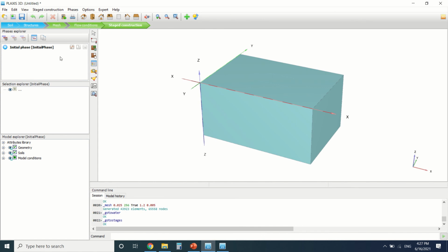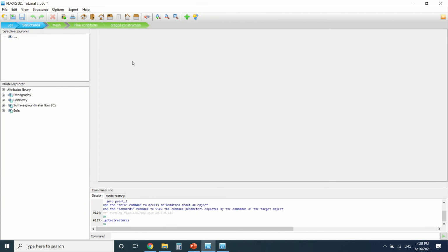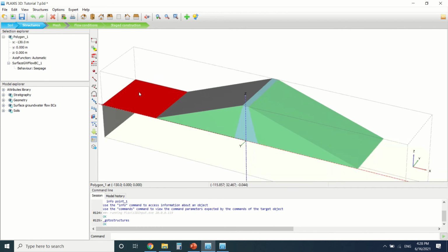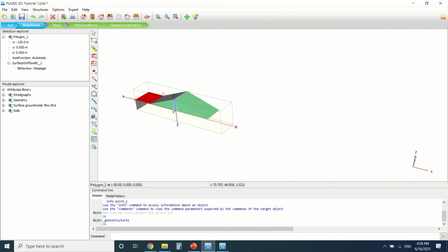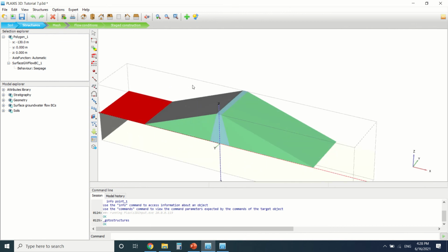So it's the same. So now I'll upload an exercise that I've already made on Plaxis for you to see the results, and I can explain the results deeper in details. So this is an example that I've already uploaded on YouTube. We can see here the structure. This is the polygon, which is here set to seepage. These are the boundaries of the drawing.